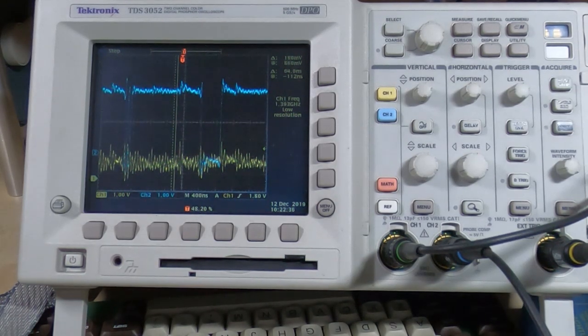So what you could do at this point is check the other channels to see whether there are possibly faults on those as well. But if there's a fault on one channel, then of course we need to change the chip anyway. I have actually checked where these two connections go to, and the output goes to the serial controller chip, and the input is from some glue logic, and that backs up the particular fault I was looking for here. So what I'll do now is replace that device, and then we'll get the analyzer back on and see if we've resolved the problem.